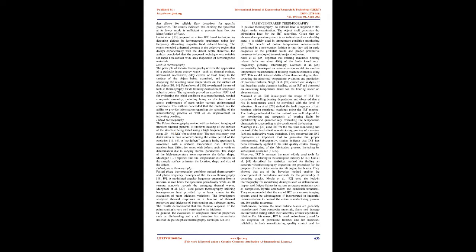Vibrothermography. Vibrothermography is a non-destructive evaluation technique used to discover surface and near-surface defects such as cracks and delaminations through observations of vibration-induced heat generation. 7 to 10. It involves exposing the specimen to a sonic or ultrasonic vibration, then observing the induced frictional heating with an infrared camera. 11.